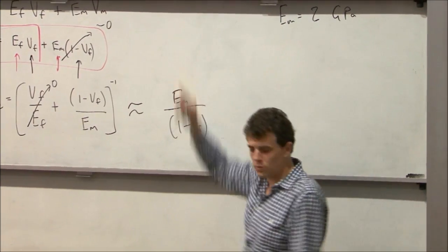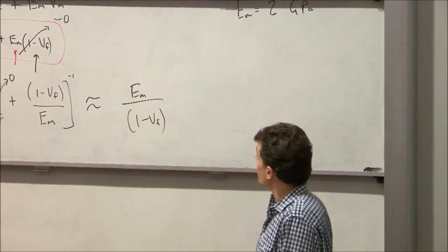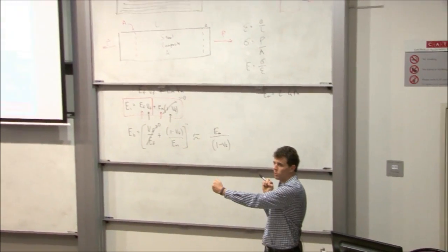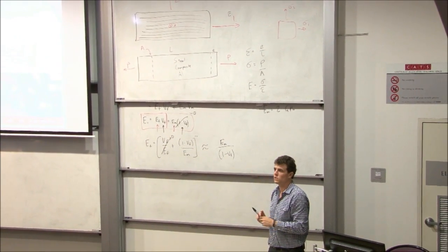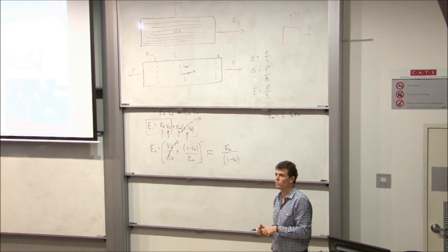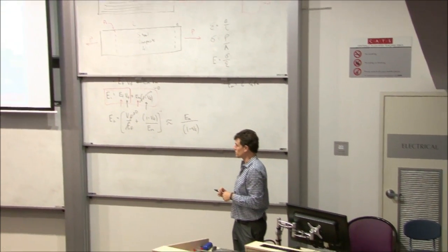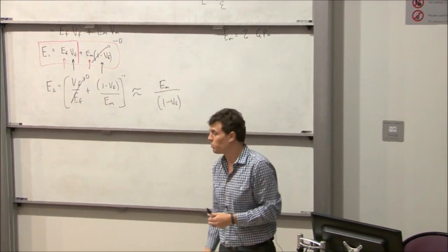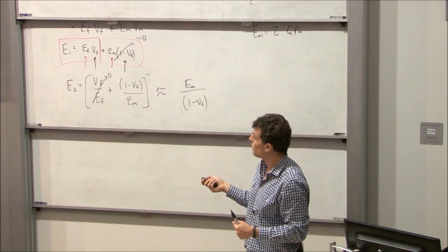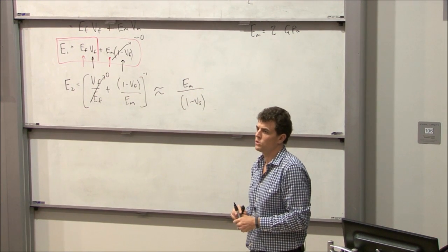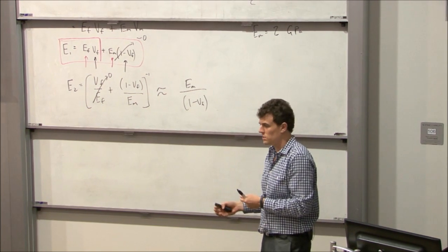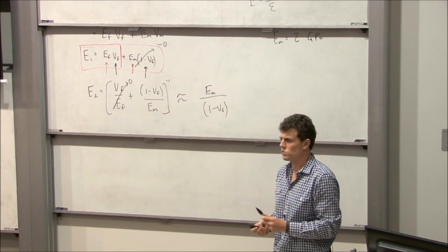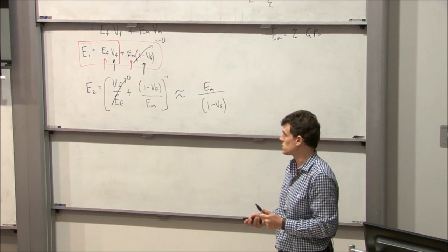So in our composite, in the fibre direction everything's going to be very stiff because it's driven by the fibre properties. In the transverse direction everything's going to be very compliant because it's driven by the matrix properties. And you can get progressively more complicated with your approximations depending on how accurate you need to be. So never go too far into this unless you need that accuracy for your calculation. And for most calculations, as we'll see, the accuracy just isn't that necessary.